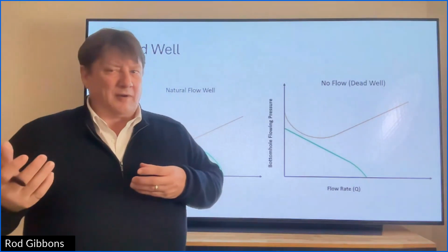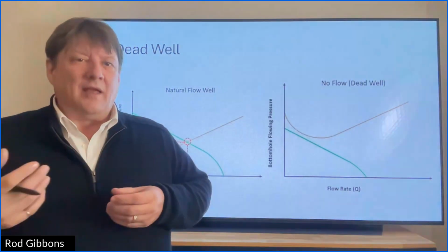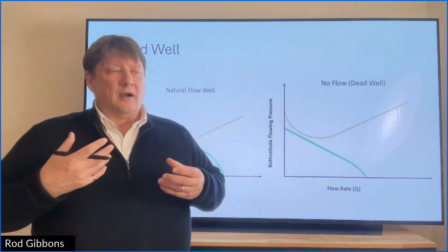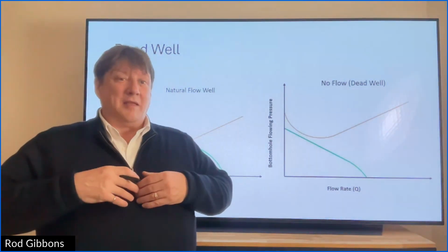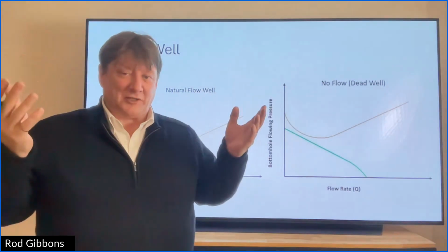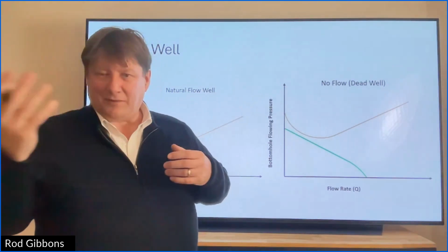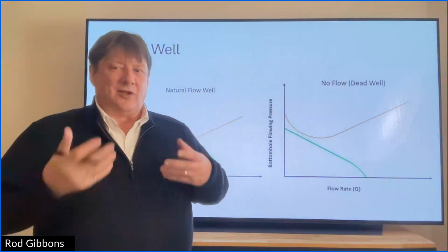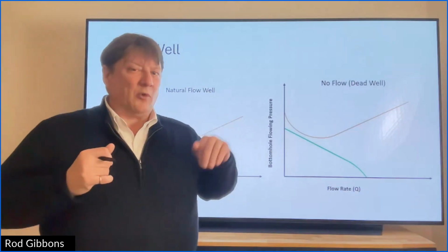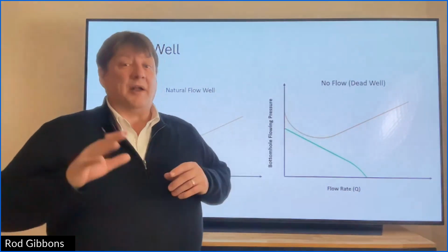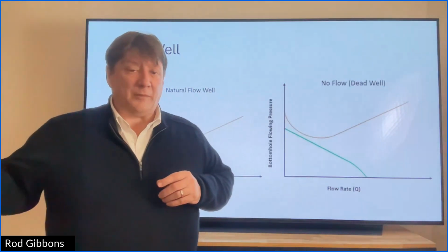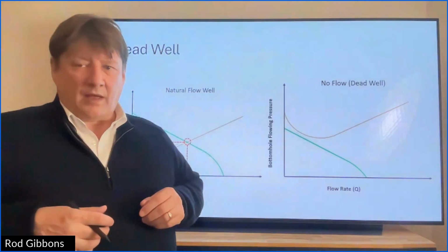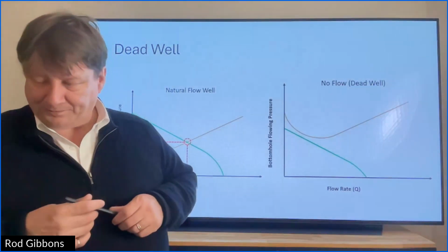There's another reference to dead well in a drilling or well control situation where, will it flow to atmospheric pressure? So if the Christmas tree gets knocked off or there's some sort of situation, so you can have a dead well that won't flow to a production system, but it could still potentially flow to atmosphere. So you still have to treat it as a live well, just from a well control point of view.